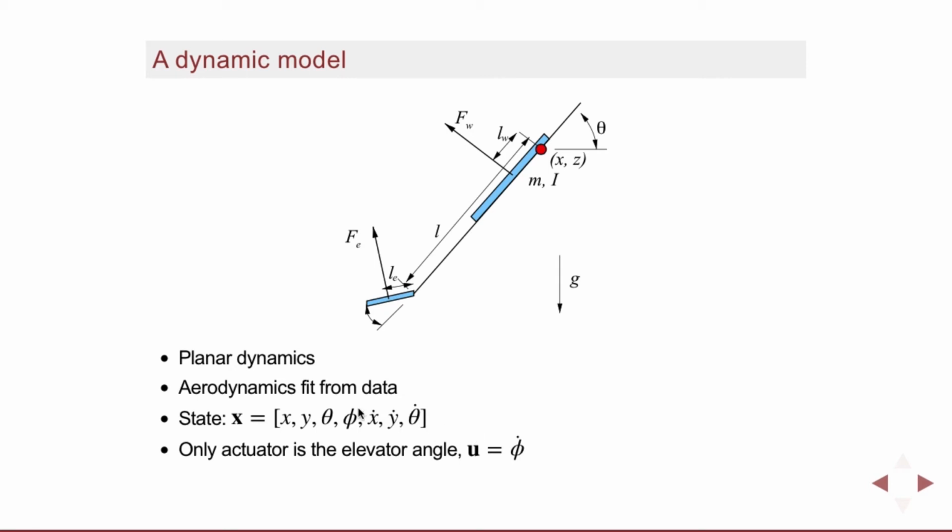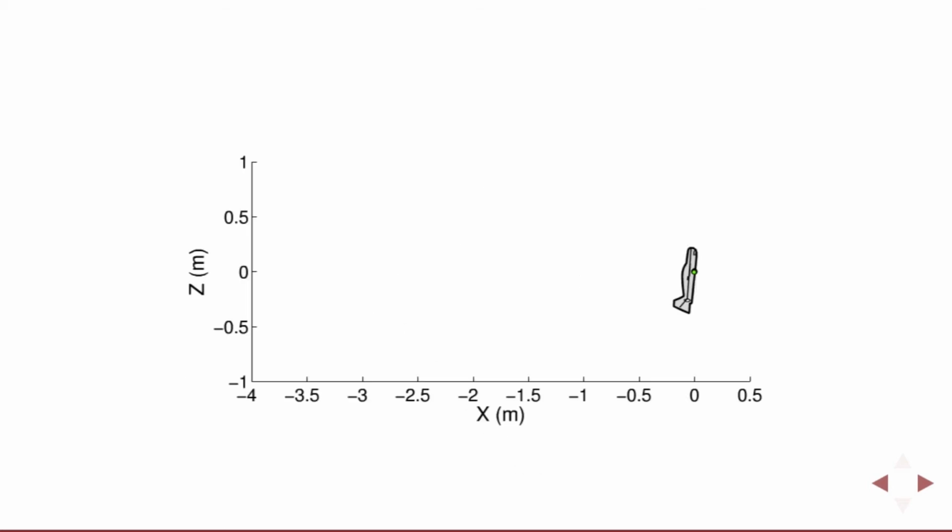And our control, we're going to assume it's a 7-dimensional state space. There's an odd number because we're going to assume that the inertia of the tail is negligible in the dynamics of the airplane, and we're going to have direct control over the velocity because that's what we had from our hobby servos. Okay, it turns out if we take our model, put it into Drake, and do some basic trajectory optimization, this is a direct collocation method now.